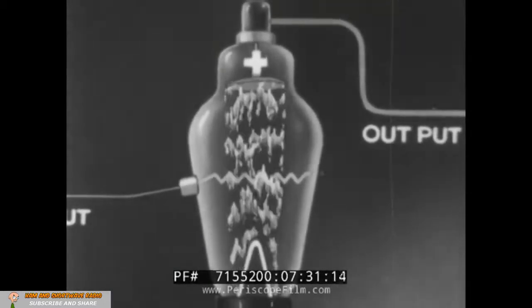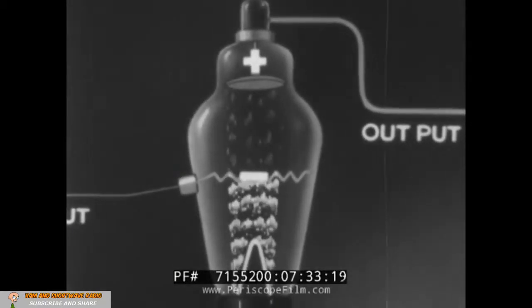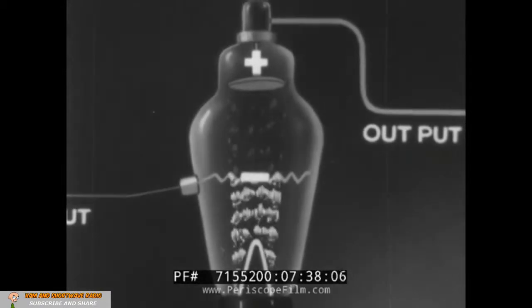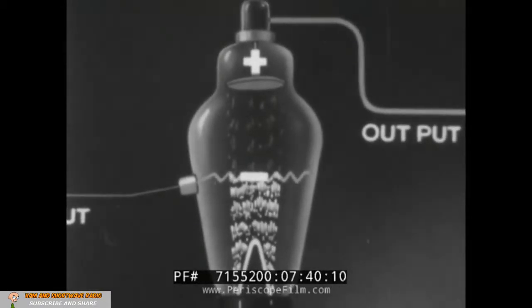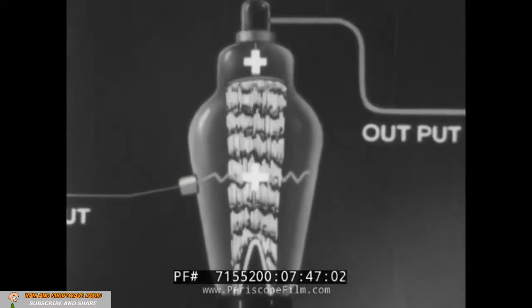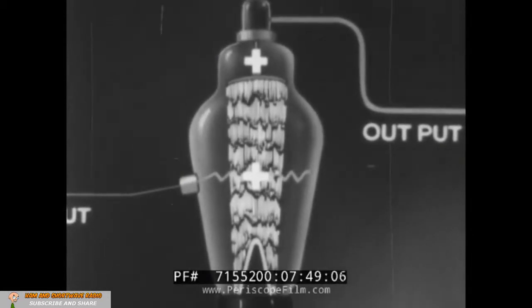At one time, a negative potential is impressed on the grid, even though it be very minute. It has a large effect in reducing the number of the negatively charged electrons which would otherwise keep flying from cathode to anode. Conversely, when the grid is positive, an equally large effect is exerted in increasing the flow of electrons from cathode to anode.